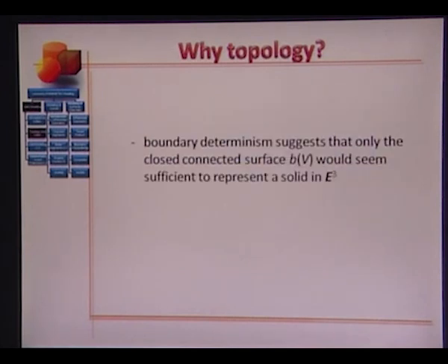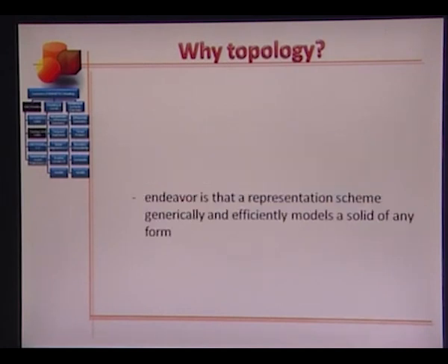The boundary determinism theorem suggests that only closed connected surface B of V would seem sufficient to represent a solid in the Euclidean space. Looks like only bounding surfaces need to be considered. The effort is that a representation scheme is required that generically and efficiently models a solid of any form.